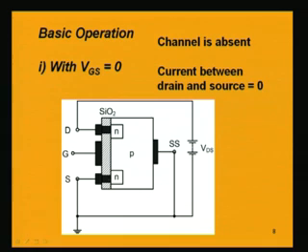So, this metallic contact is contacting with the source, and the gate terminal, which has this metallic contact, as you can notice, has no contact from the metallic contact of the gate terminal to the P substrate, because in between there is an insulator, the silicon dioxide, which is in between the gate terminal and the P type substrate.